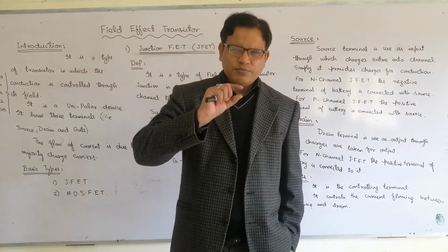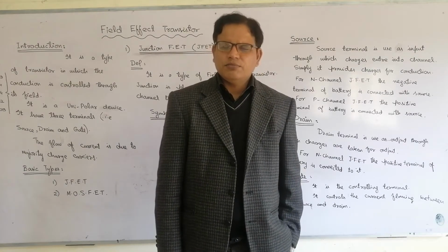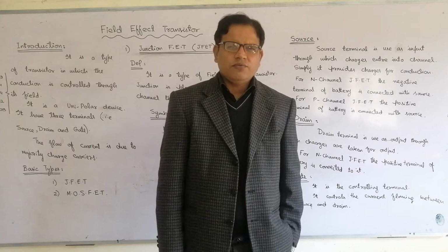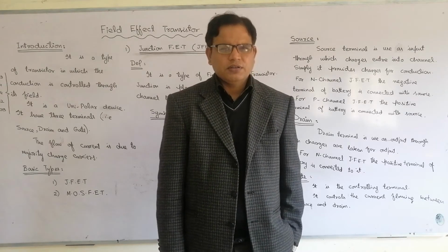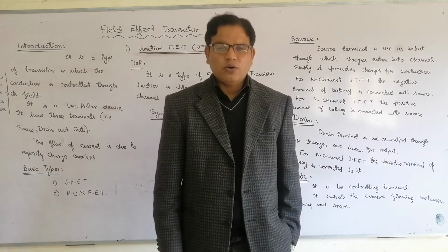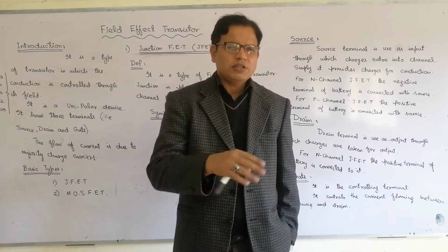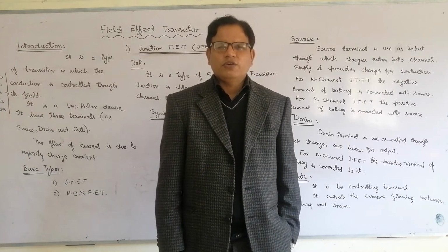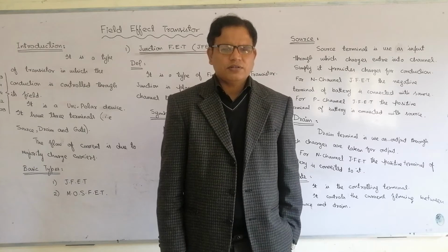That was the simple principle of the transistor, in which I briefed you that the base emitter junction should be forward biased and the base collector junction should be reverse biased. Only in this case do we also have to use the two batteries. These are the two basic principles of the working of a common transistor, NPN transistor or PNP transistor.